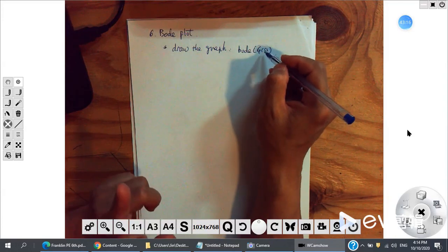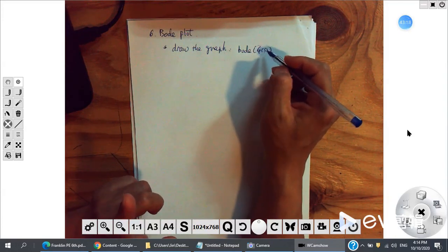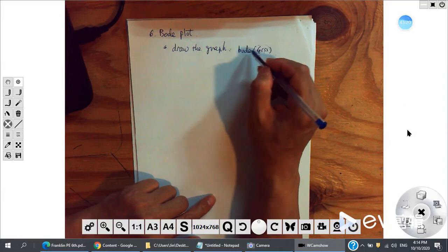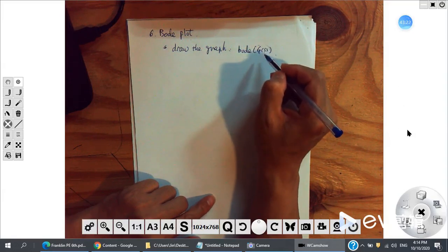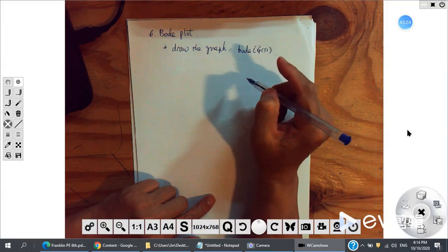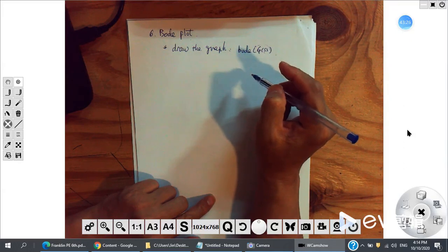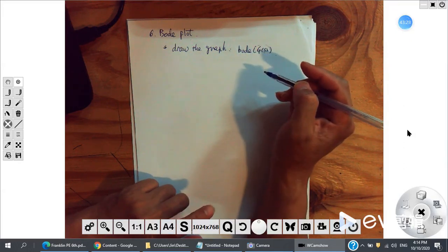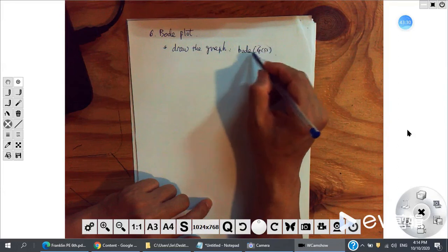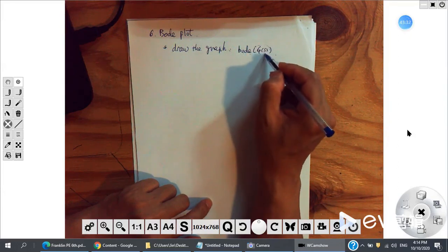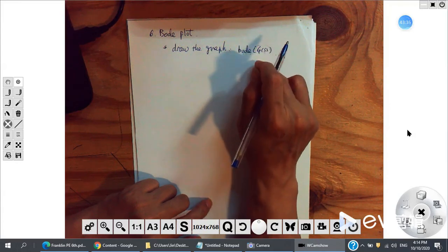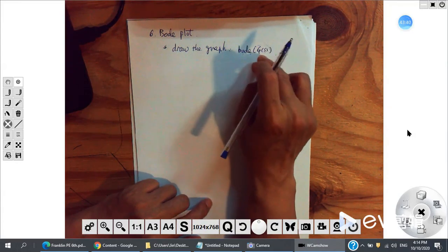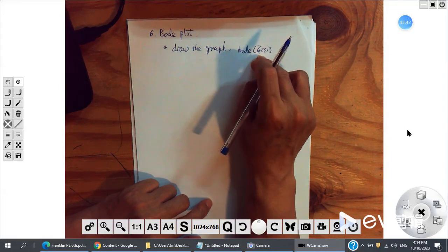In the root locus, you use rlocus of G. That G is a part of the feedback system, and the locus is for the whole system. And this one, bode plot of G, is just for G. This G can still be a part of a feedback system, but the bode plot is just for G itself. Right. Yeah, things like that.